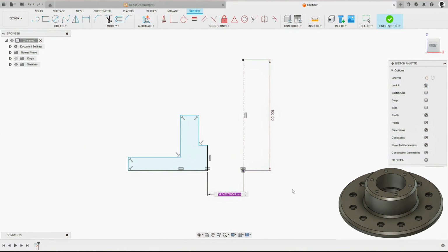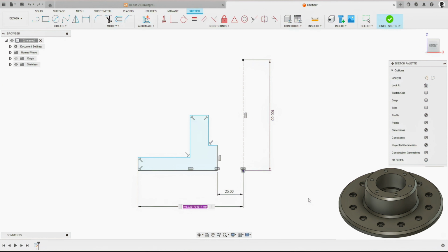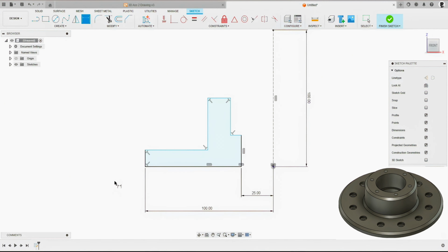And as for the drawing, we can see that we've got a 50 mil inner diameter below that recess. We need to divide that by 2, so put in 25. And then from the outer point here to the center point here, we have a dimension of 200 divided by 2, so 100 mil. We've got a wall height here of 10 mil. Put that in, 10 mil. We've got a distance from this line to the origin, and that is 100 divided by 2, so 50. And then we can do this line to the origin, which is 58 divided by 2, so 29.